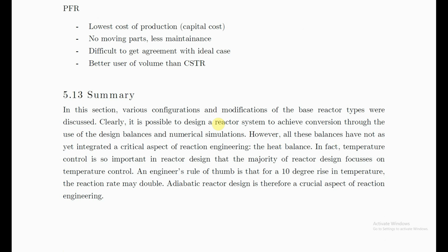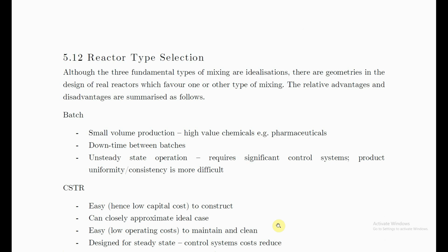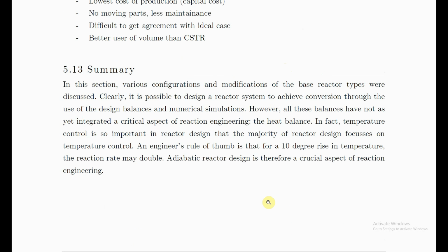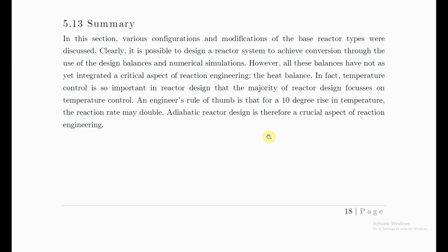And then we can also look at how to design for these alternate types of cases and how to develop the material balances there. So that's a fairly good grounding in this case of isothermal operation, where the temperature is fixed and constant. We have a full grasp of our material balances, and we can estimate the volume of the reactor. And so we have a good grounding in terms of actually starting to design our reaction processes.